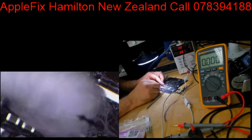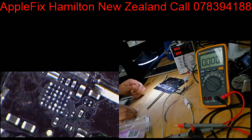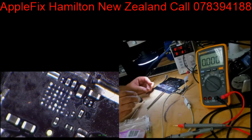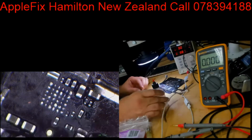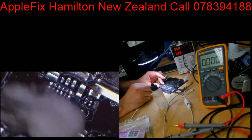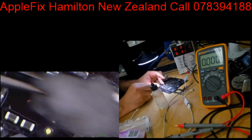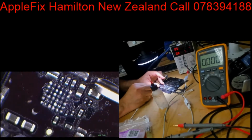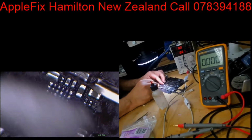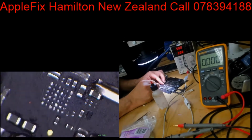And I see a little bit of cones on two of the pads, which we will align later. So it looks okay to me. We'll just give it a clean, and then it's ready to adopt the new U3500 TriStar IC.